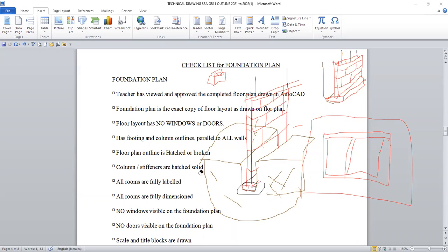So what I'll be teaching you to draw is how to generate the foundation. I would like you to take note, however, that the width that we dig is relative to the width of the foundation. Typically, the width of the foundation is 3 times the wall. And here is normally our minimum, 450 millimeters.